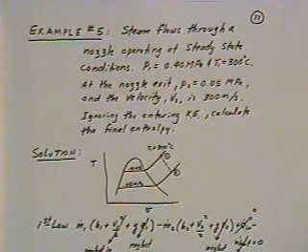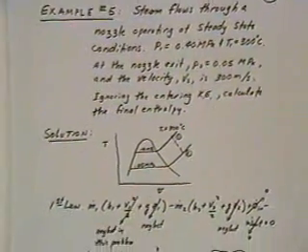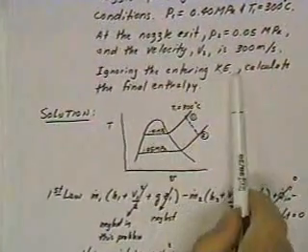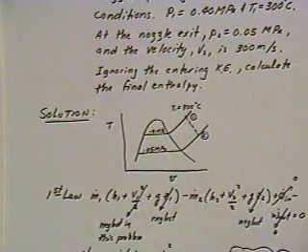The other usual assumption is that there is no work done, the heat transfer is 0, the change in potential energy is 0, and so we're left with an expression here where we're going to throw out all of the terms except the enthalpies and the exit kinetic energy. We're told to ignore the entering kinetic energy as well.